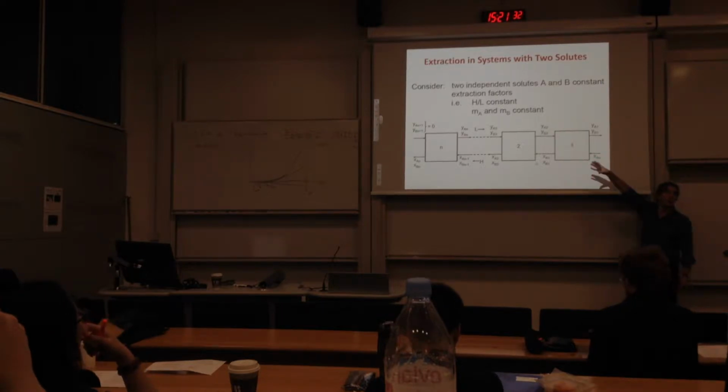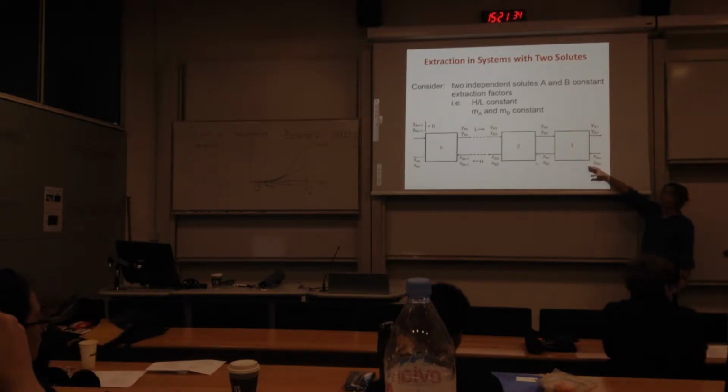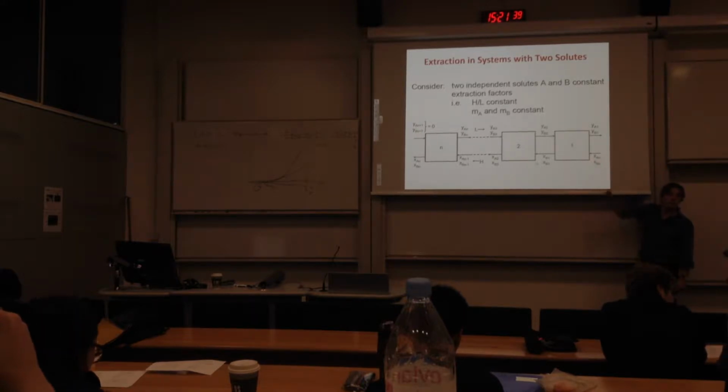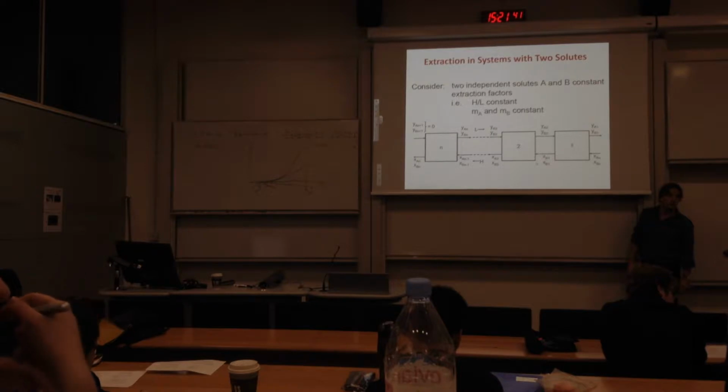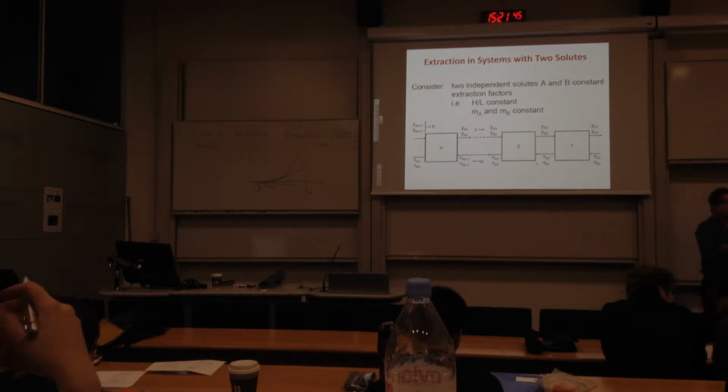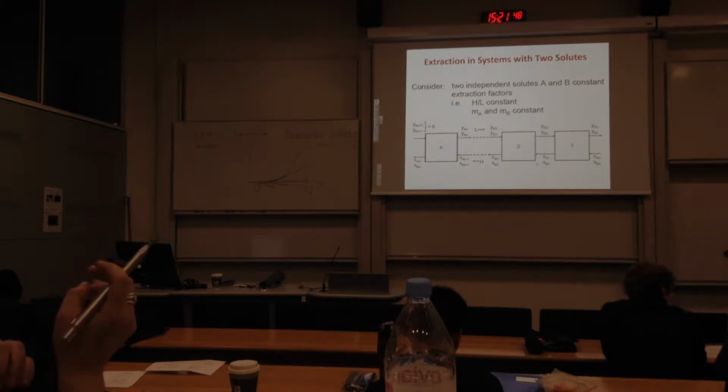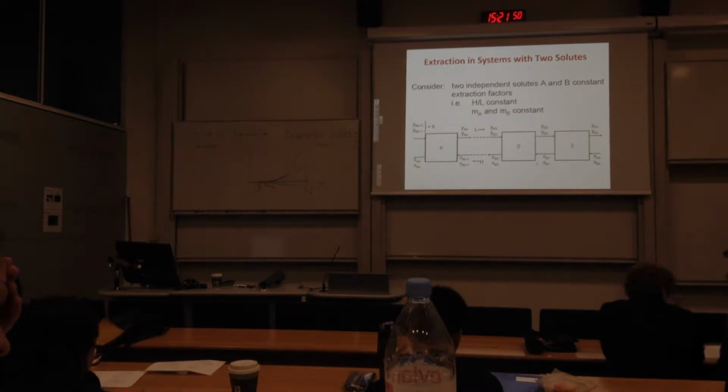For example, don't use acid, because that increases the affinity of uranium for the aqueous phase. Or you can even run the very first stage without the phosphate in the kerosene, because uranium is soluble in it exactly because of the phosphate. That's the reason why phosphate is used in the kerosene phase: to promote uranium extraction. If you don't want to extract uranium, and you want to extract something else, you will use the opposite condition. But yeah, that's a good point. So again, conditions will need to be tailored to the separation we want to achieve.